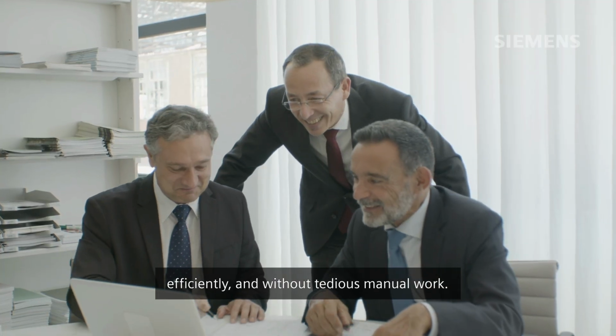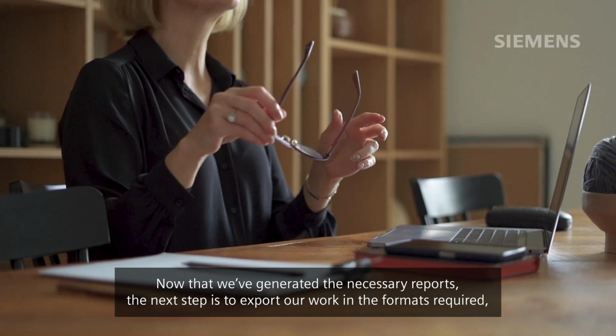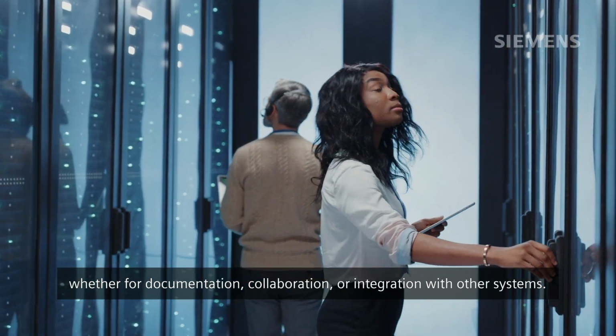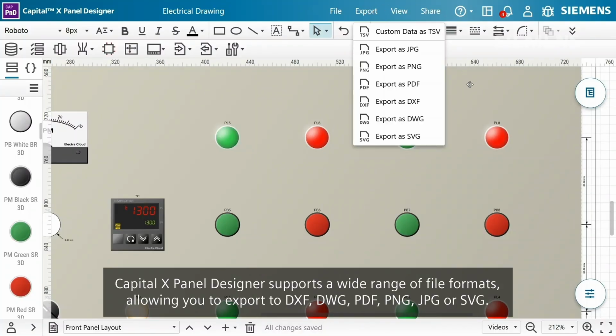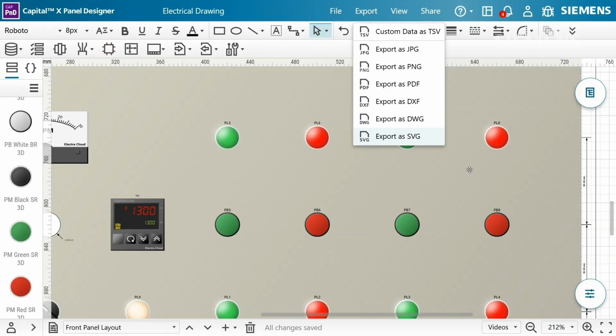Now that we've generated the necessary reports, the next step is to export our work in the formats required, whether for documentation, collaboration, or integration with other systems. Capital X Panel Designer supports a wide range of file formats, allowing you to export to DXF, DWG, PDF, PNG, JPEG, or SVG. This gives you the flexibility to share and reuse your designs however you need.